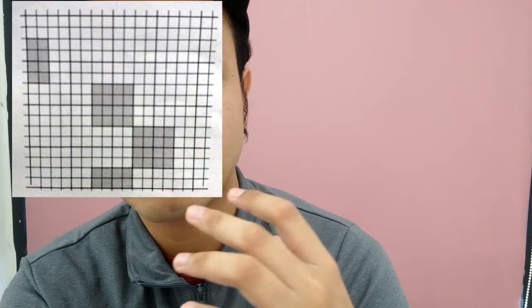The transform coding process is a two-stage process. In the first stage, the 4 times 4 blocks are transformed using the core transform. In the second stage, the DC coefficients for each macroblock are collected together. The macroblock size being 16 times 16, this means we end up with a 4 times 4 block of DC coefficients for each macroblock. These coefficients are transformed using the core transform. This process of decomposing the low frequency components of an initial decomposition will become more familiar when we look at subband and wavelet based compression.